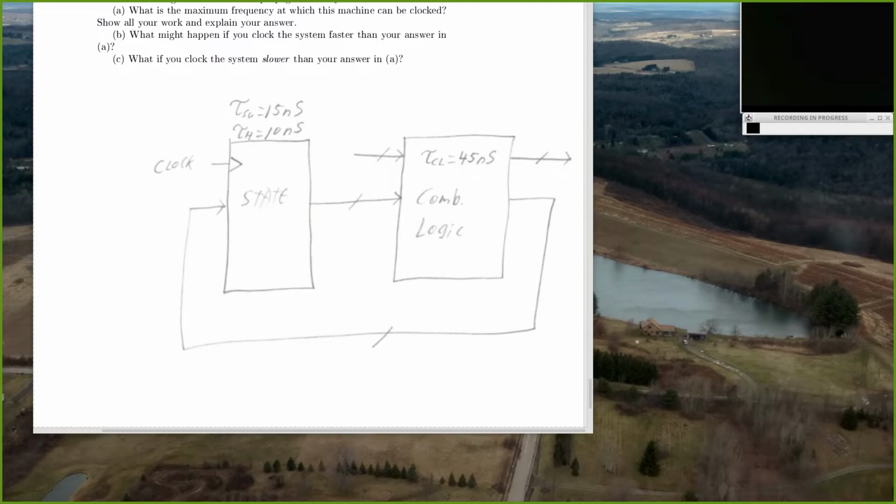But we can't really use a truth table directly to describe what is yellow based on those 3 inputs. It's more complex than that because this is a sequential circuit. Just because east is 1 and west and south are 0, we don't know if east is going to be green or it's going to be red. If there's nothing else that's happened for a long time, then east will be green. But if there was a car that just showed up on the east, right now east might still be red, and then in 2 seconds it might be green.